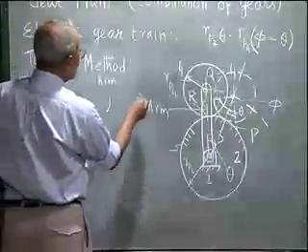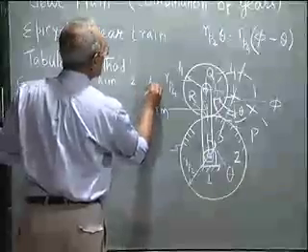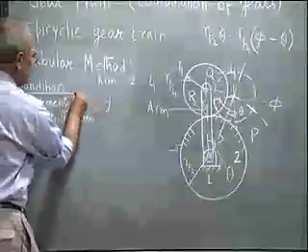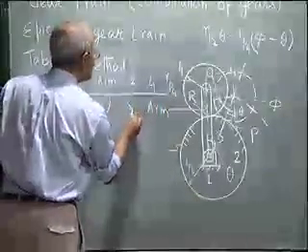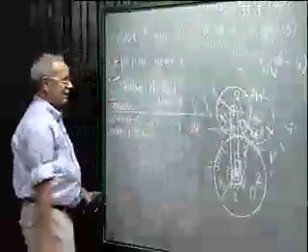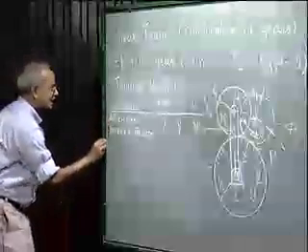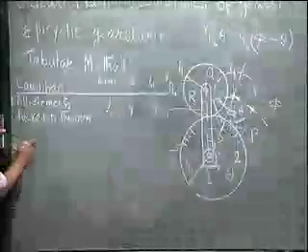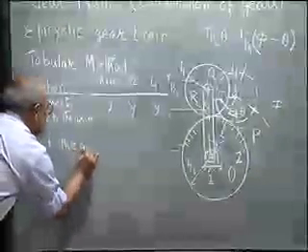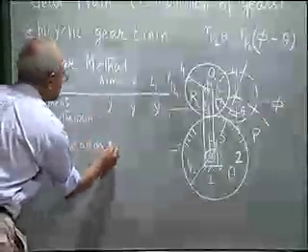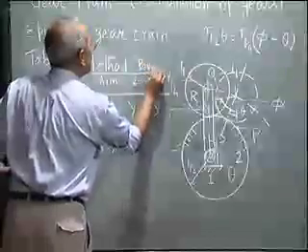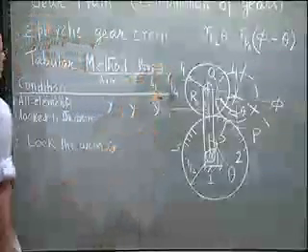Then gears 2 and 4, because they are locked to the arm, under this condition, if I give arm y revolution, I will get y revolution to all the gears. And the second condition I consider is to lock the arm. That doesn't allow the arm to move. That means these are the revolutions of arm, gear number 2, gear number 4.